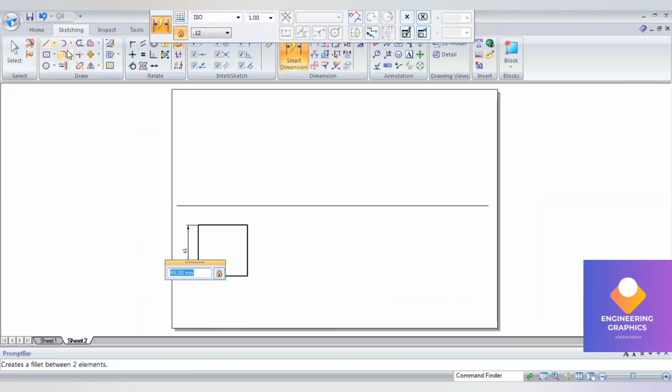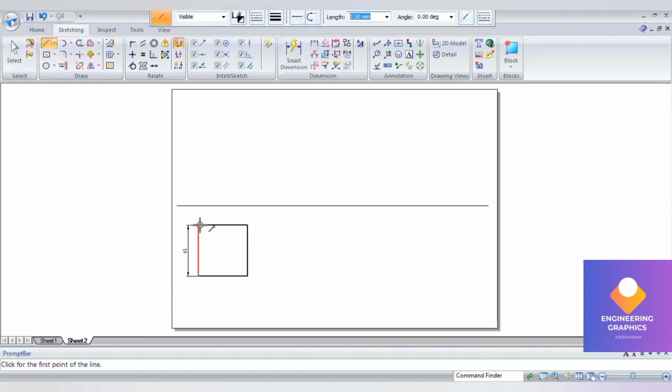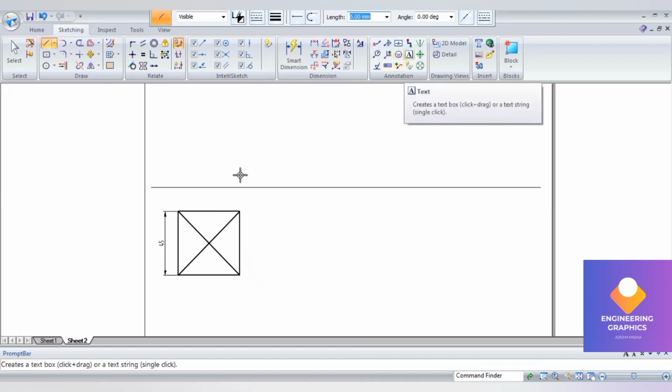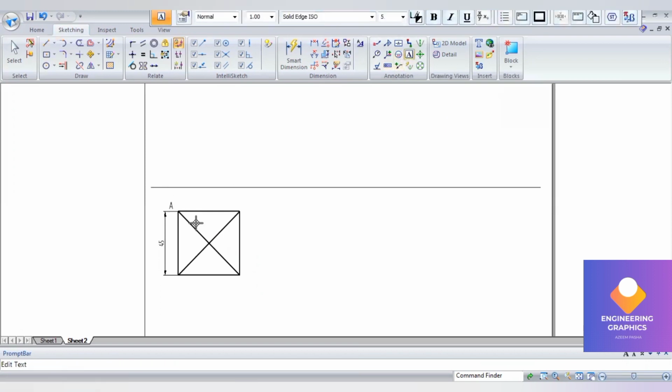So now this is the pyramid. The inside lines we should draw, that is thick lines, because these lines are slant edges. We should be drawing these thick lines. Okay, now mention the namings for it. Mention with the small case letters.